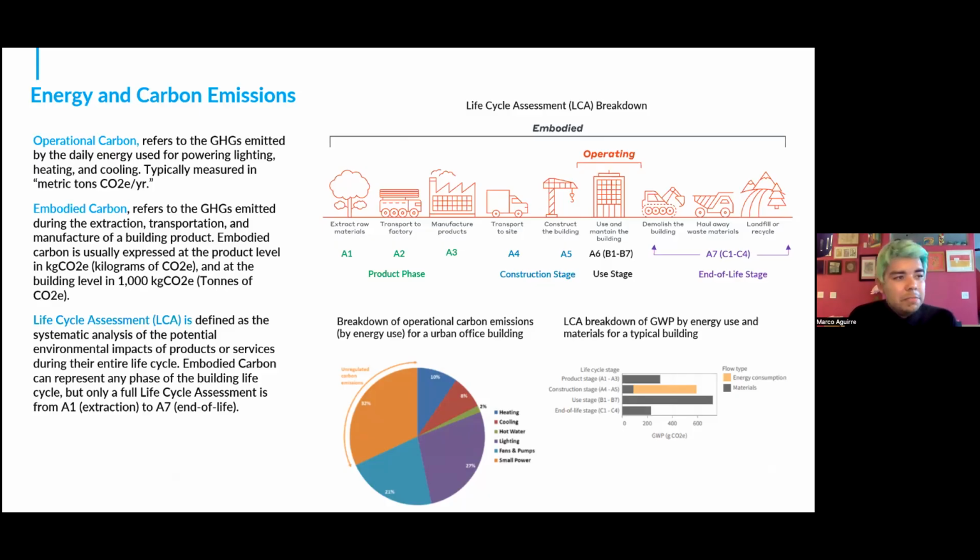Very few projects ever go for creating a life cycle assessment. So part of my job is also just to let you know to only really worry about the product stage and use stage if you're looking at embodied carbon. It can be incredibly expensive to calculate all these stages. There are a lot of tools out there that make it easier and easier, so eventually, when that's possible, definitely go out of your way to calculate a full building LCA.